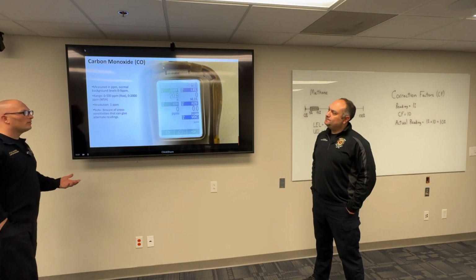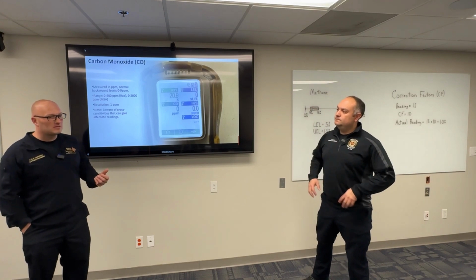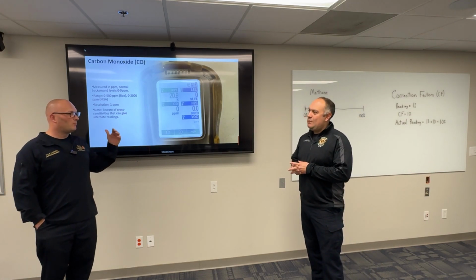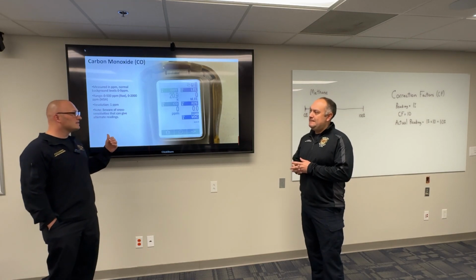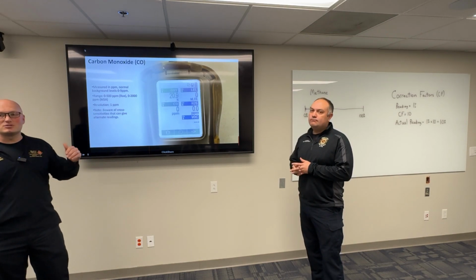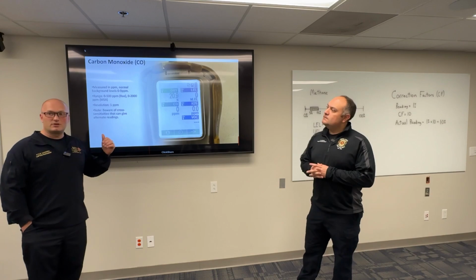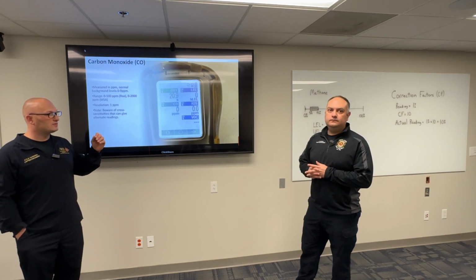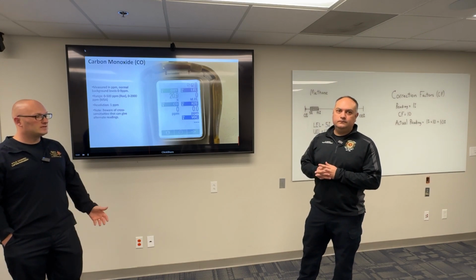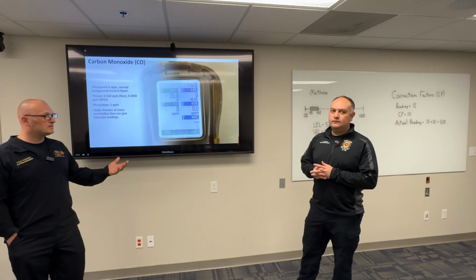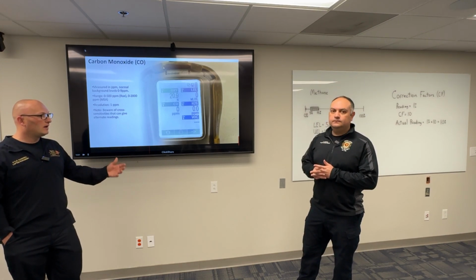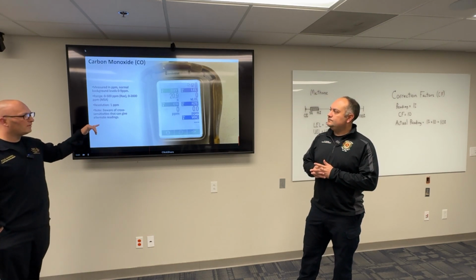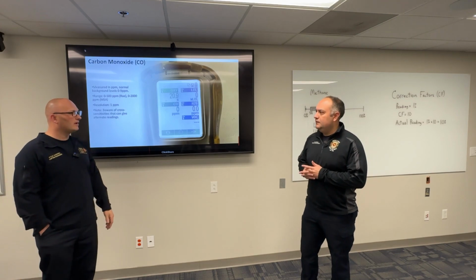CO, I think this is one of the most common ones we do, especially this time of year in the fall and early winter. We run these calls multiple times a day. So the biggest thing with this is to dive in and really consider the alternative sources, and really understand what we're looking for with our CO readings. Where are we going to find these CO readings in the house? When do we start metering and everything like that? And the cross sensitivity on the CO readings, what are some things that can give us that?